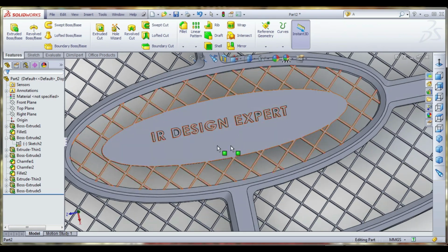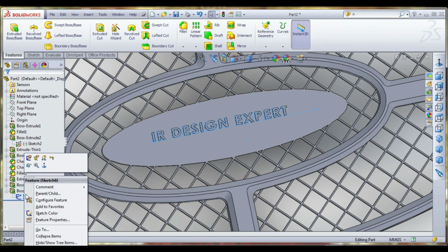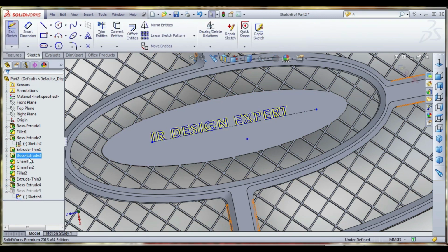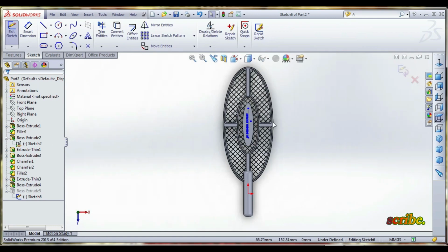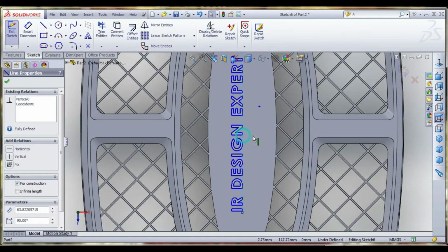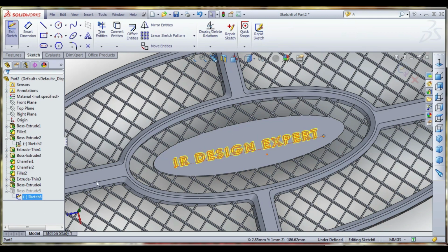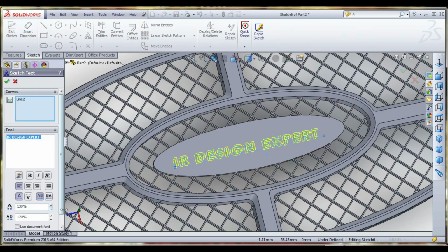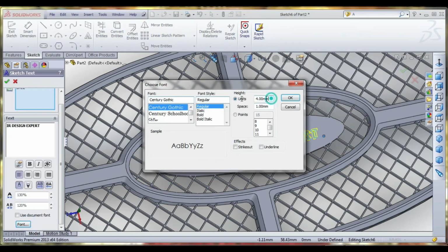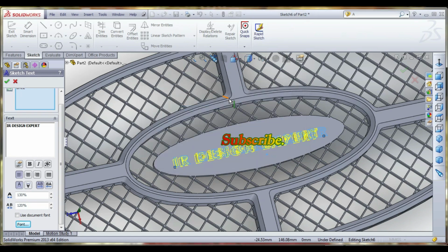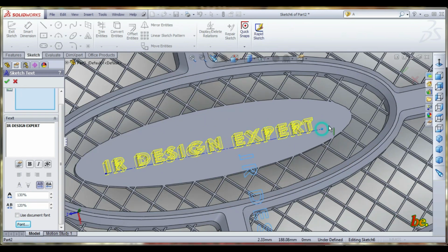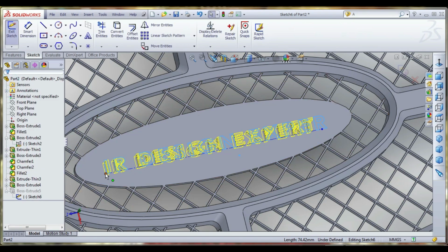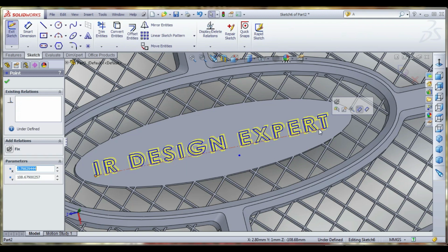Now I'm going to edit the text. Just drag the center point, center line, and then increase the text height to 0.5, and then adjust the center line. It should make a particular line. We should drag it to cover the particular space.